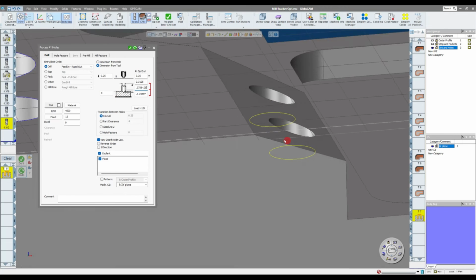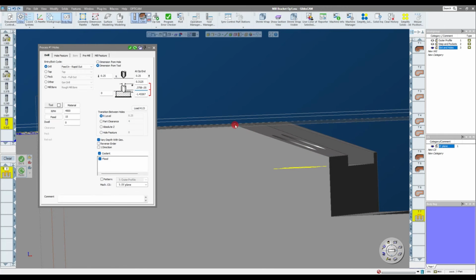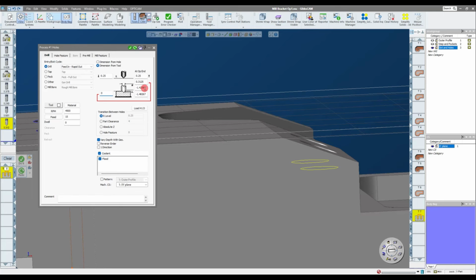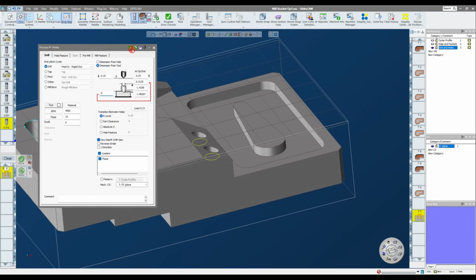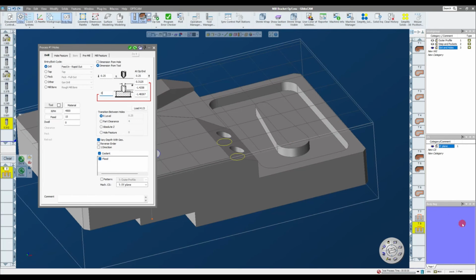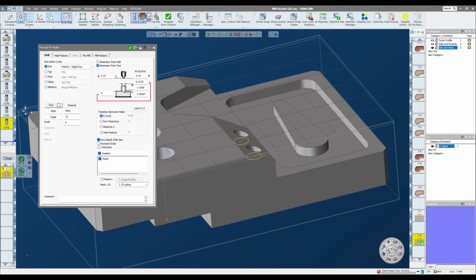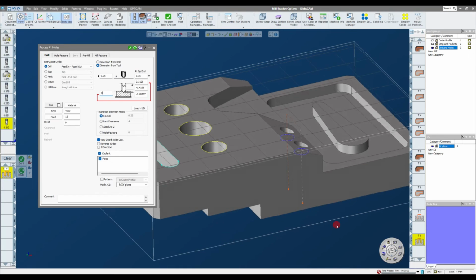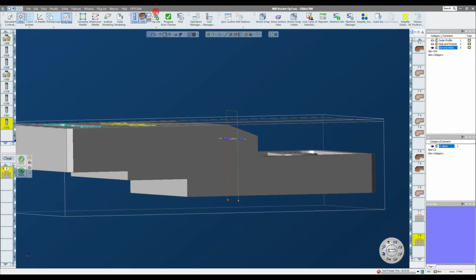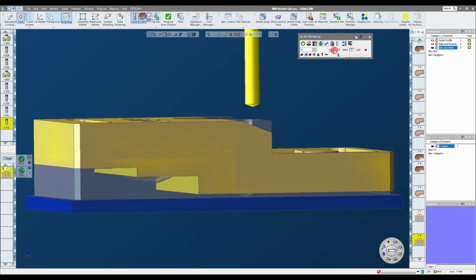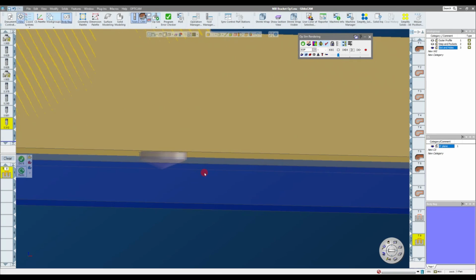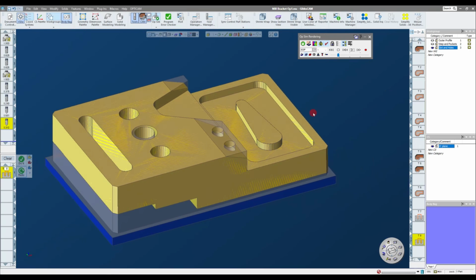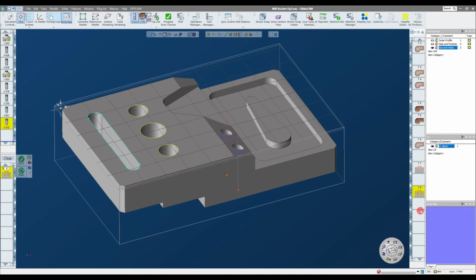I am going to be cutting from Z0, because remember, this angled material is still square, so I am starting at this Z0 there. And then I could just simply click do it, and I've got my next drilling cycle. Oops, I forgot to select the correct holes. I need to select these 2 holes. Redo. There you go. And again, if I go into my OpSim and run those, you can see where they're popping through the bottom of my part. All right, we're progressing. I'll hit deselect on the right, clear, file, save.